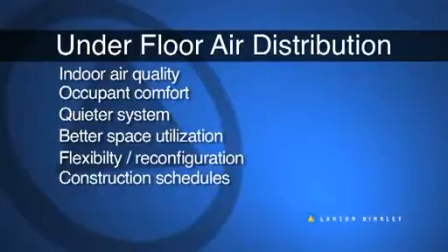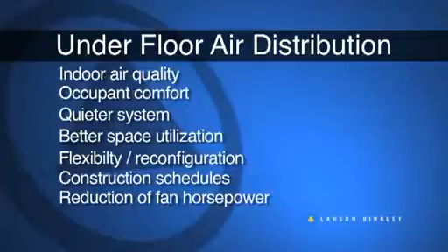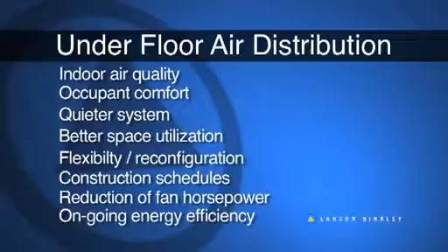Enhanced construction schedules due to reduced labor. Reduction of installed fan horsepower, which is a real dollar saver. And ongoing energy efficiency, which alone is probably reason enough to consider underfloor air. The bigger the building, the greater the savings. In many situations, the benefits of a properly installed underfloor air system are so overwhelming that it's worth adjusting our thinking to accommodate this innovative way of delivering conditioned air.